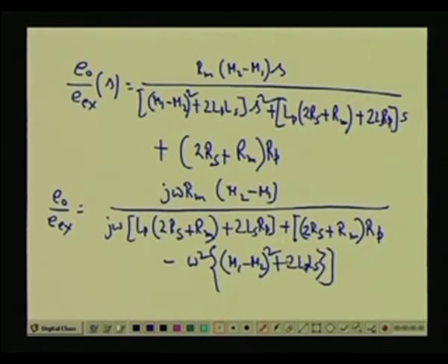See, now if I want to make the input output phase shift 0, then you see that this term, if I take a different pen, this term and this term will be 0. Then j omega j will cancel out, so it will be only the no imaginary part. So, there is no phase shift between input and output, otherwise there will be phase shift, right.